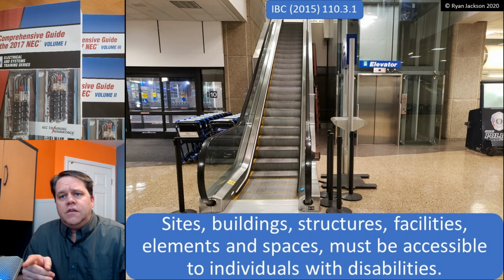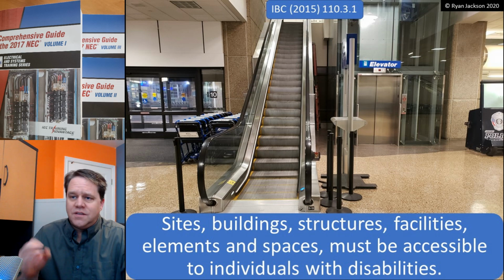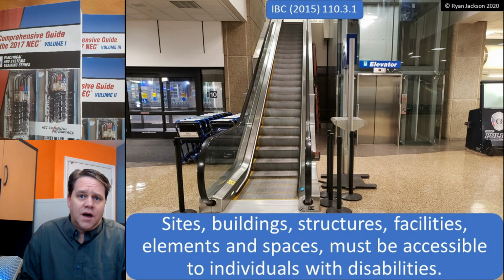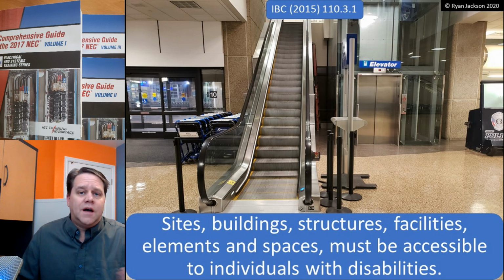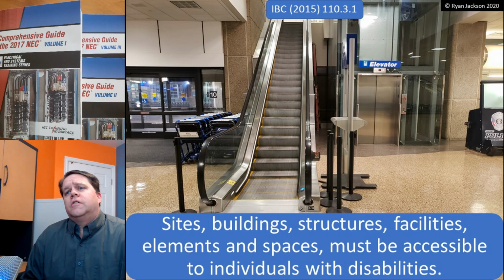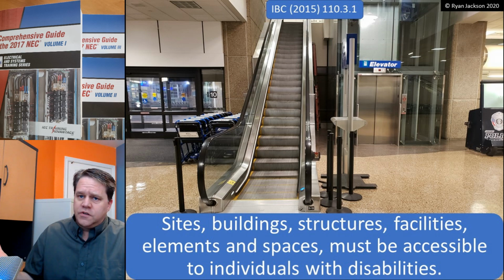Now, this is from the International Building Code. It starts out by saying that sites, buildings, structures, facilities, elements, spaces, everything has to be accessible to people that have disabilities. Everything within the scope of the IBC. And that's why I say it does not include single-family dwellings, because single-family is covered by the IRC, the International Residential Code, not the International Building Code. But if you fall into the scope of the IBC, then everything in the building, all the sites, all the facilities, everything in it must be accessible.